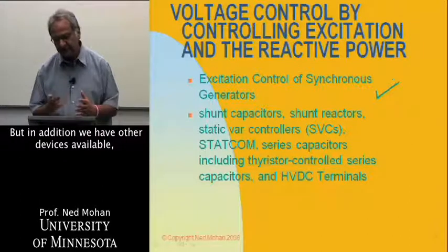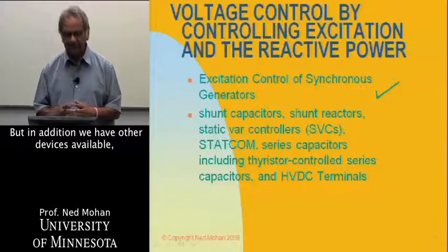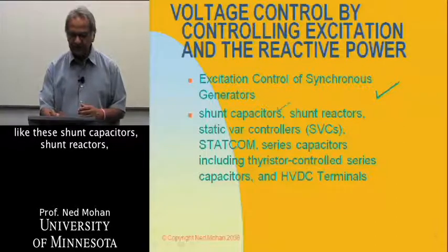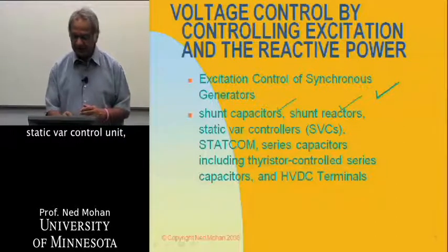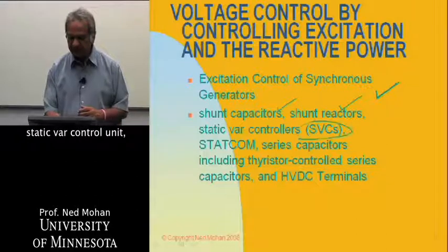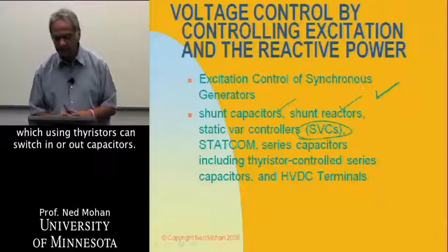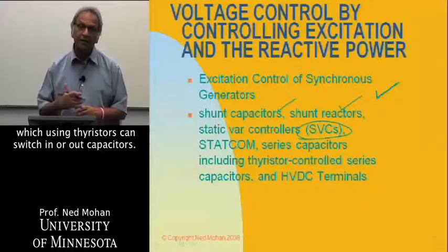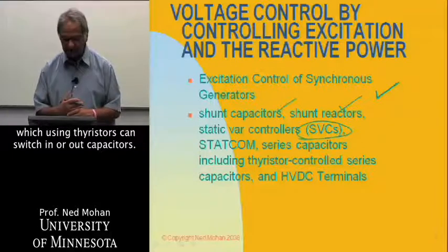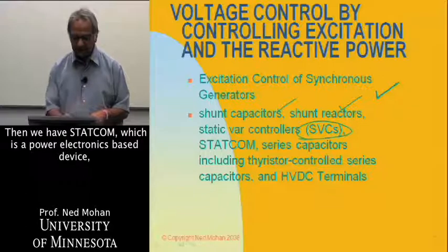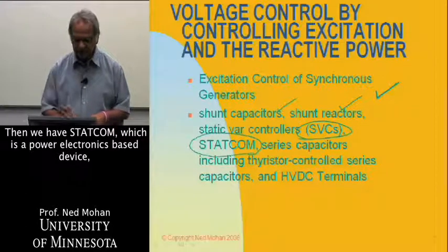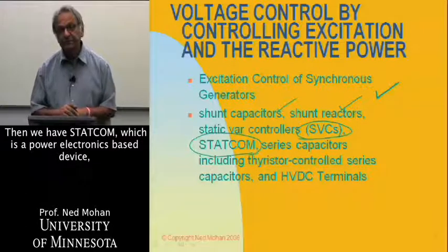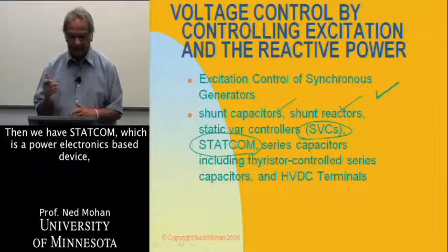But in addition, we have other devices available, like shunt capacitors, shunt reactors, the static VAR control unit, which using thyristors can switch capacitors in or out. Then we have STATCOM, which is a power electronics-based device,